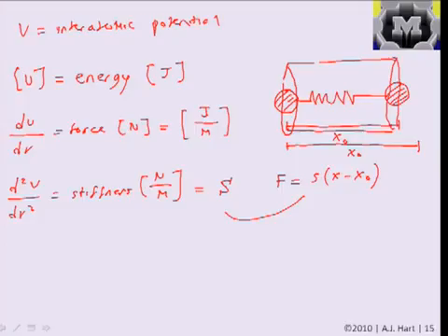And so let's define a cross-sectional area as approximately equal to x naught squared, or like, you have about one circular area of radius x naught as the cross-sectional area of this piece. So then, if we go back to our classical definition of stress as force over area, which we know is the Young's modulus times the strain epsilon,